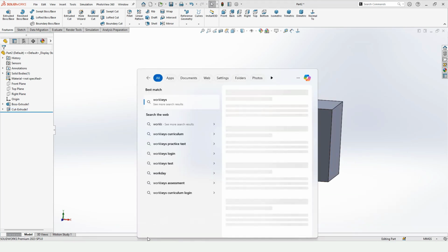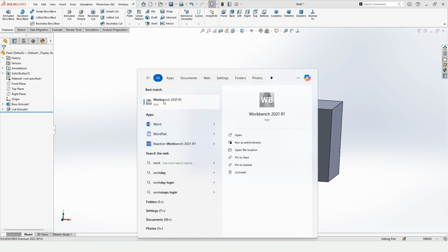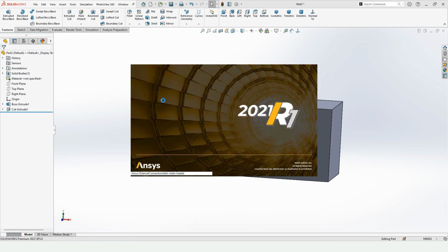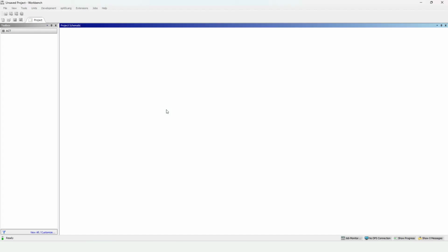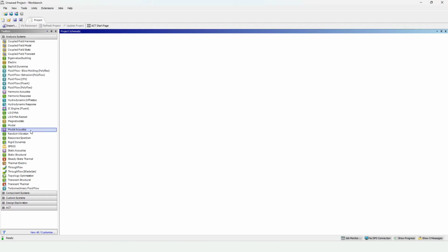So I'm opening Ansys. So you have to type Workbench and then click on it. The Ansys will get opened. Okay. So here we have different types of analysis systems. We need static structural. So you need to double tap on it. Okay, and here you can rename this title. It's an optional step. And now I'm going to explain you each of these steps.